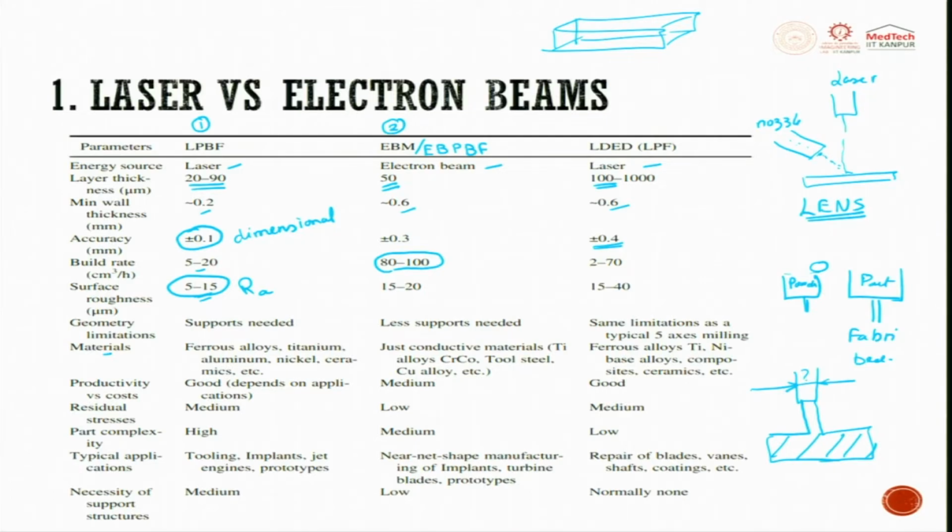Here the process parameter optimization is always difficult in each of these processes, and again generating these powders in a consistent manner is also a big challenge. That itself is a huge challenge. There is a lot of work going on. For metal atomization, people are working on nozzles, what the spray has to be, and other things.